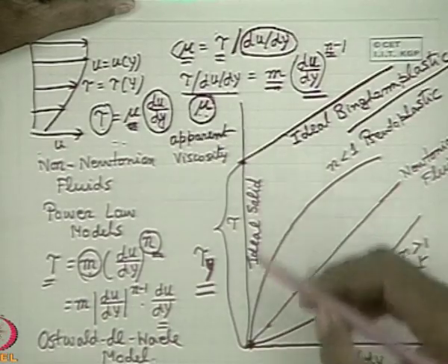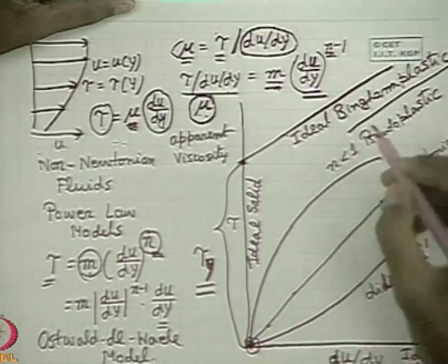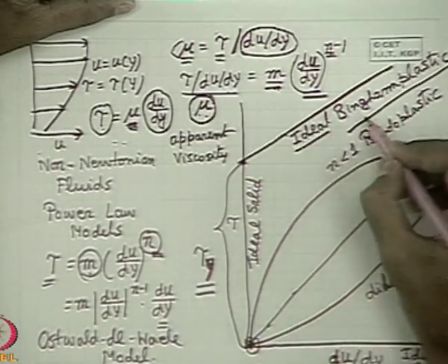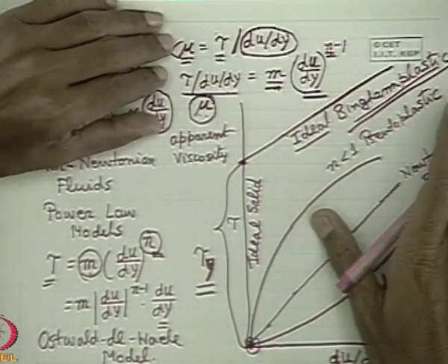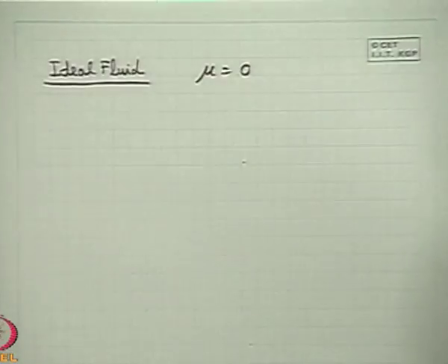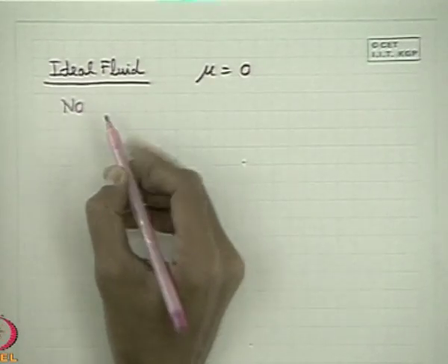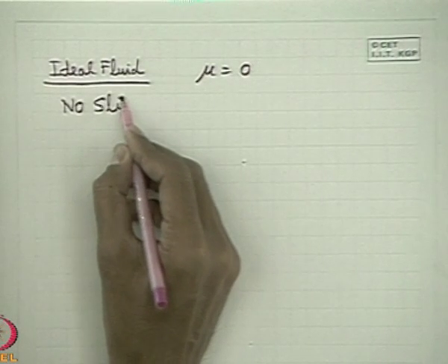So, the classes of substance which do not follow this, that means there is a yield stress, violate the basic definition of the fluid. So, for these reasons, the Bingham plastic is not considered as a fluid. Well, next I go to another very important piece of information, the no slip condition.